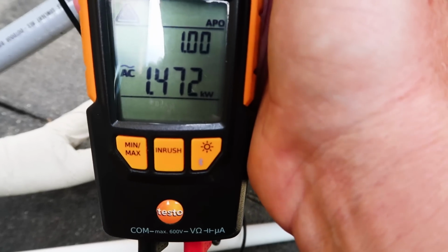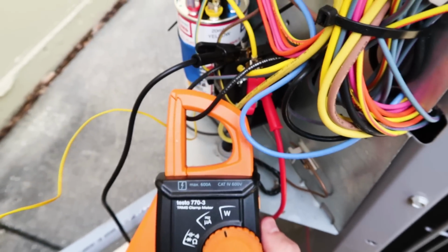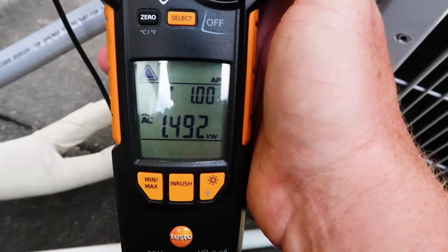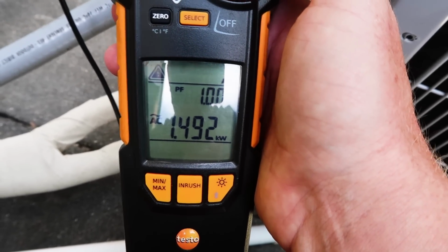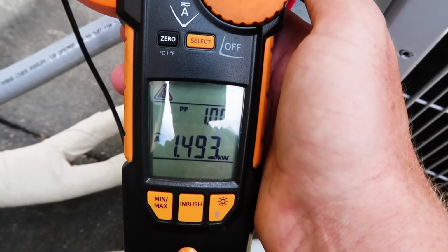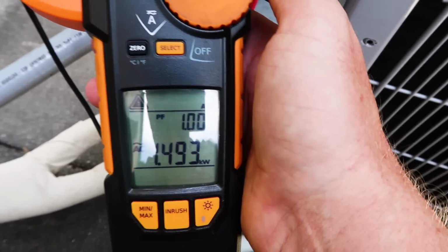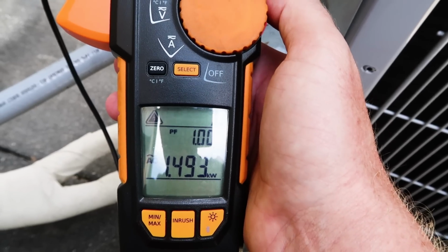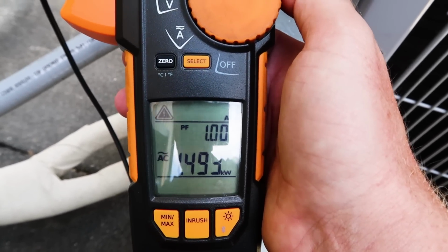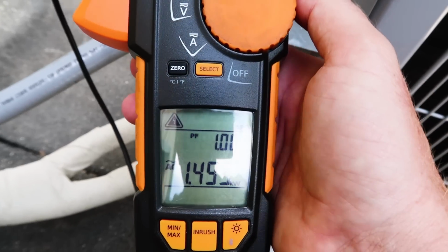I have it connected with alligator clips. I'm measuring the wattage and the power factor, and it's showing that I'm at unity power factor, which means the capacitance is doing its job to overcome the inductance. That's a whole other conversation, but I just wanted to make sure that the capacitor is indeed functioning properly, and it definitely is. So everything's sized properly.